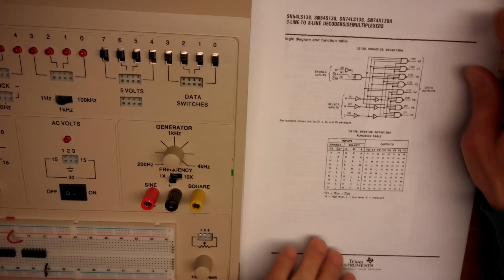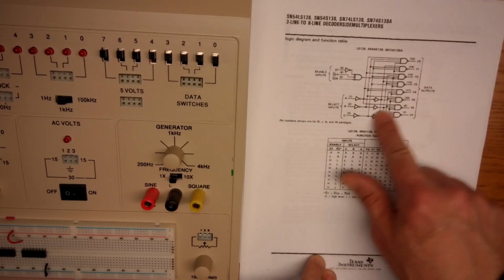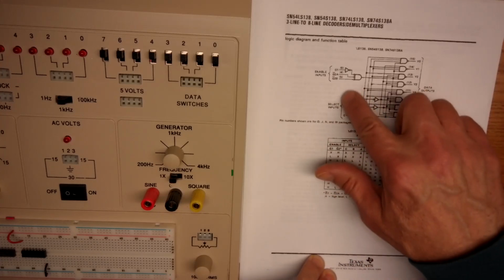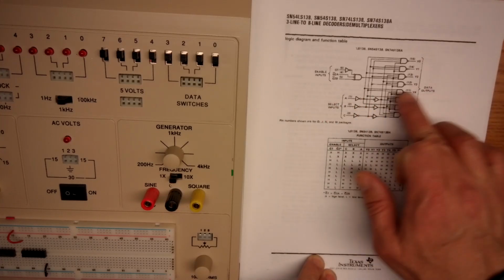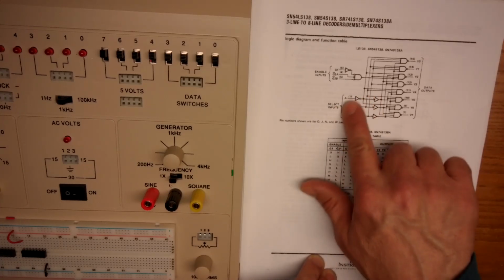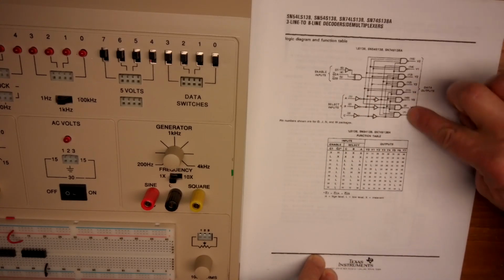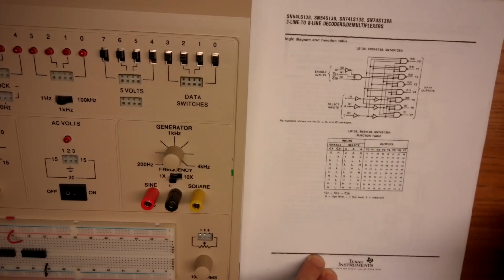If I go to the second page, by the way, if you just look at here, it'll actually give you a picture of here is what my decoder looks like. So I have a 3-input decoder, 8. It's called a 3 to 8 decoder. So whatever binary value these three numbers represent, we're going to set that specific output. Notice this is actually built with NAND gates and with a couple of inverters.